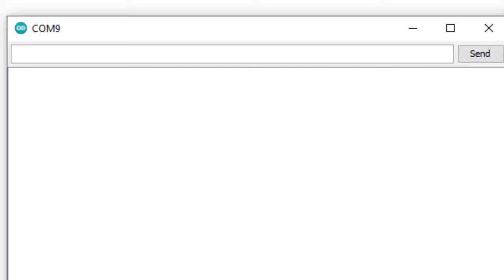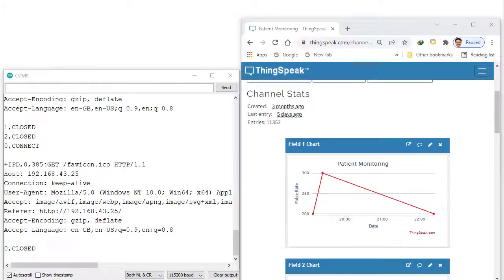After the operation of ESP8266 as a server, I need to close it. Means I need to close CIPSERVER, and the command is AT+CIPSERVER=0.